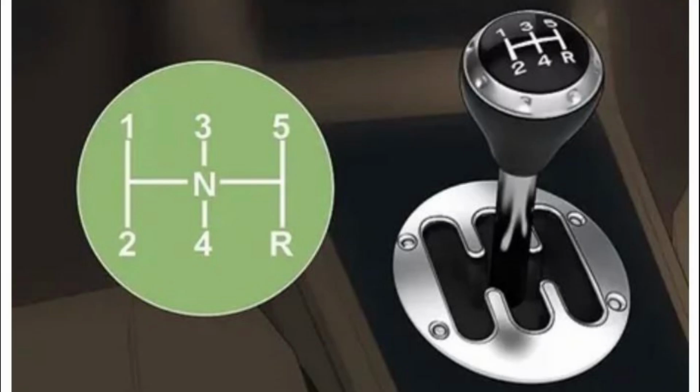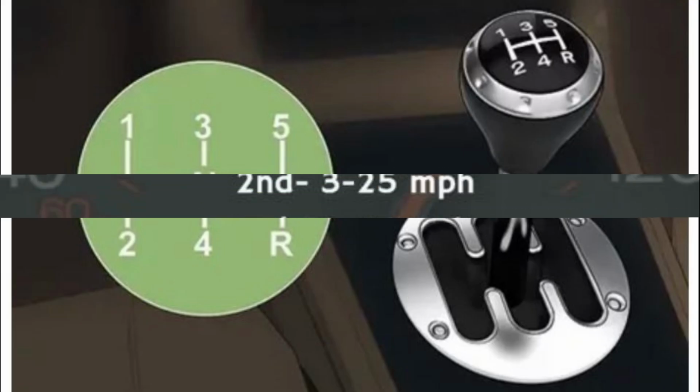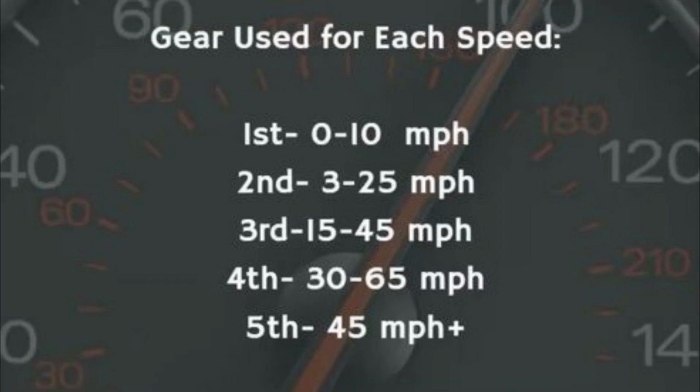There are several types of automobile gearboxes used in modern vehicles. Manual transmissions require the driver to operate the clutch and gear lever to change gears, offering better control and simpler construction. Automatic transmissions shift gears automatically using a torque converter and hydraulic or electronic controls, providing greater driving comfort. Continuously variable transmissions use belts and pulleys instead of fixed gears, allowing seamless acceleration. Automated manual transmissions combine a manual gearbox with automatic shifting, while dual clutch transmissions use two clutches to achieve very fast and smooth gear changes.